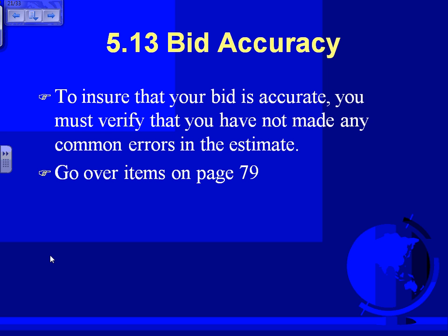Using improper estimating forms, using suppliers' takeoff quantities for quotes. Rely on verbal suppliers' quotes. Then when you get to a written one, for quotes, guys, you always get them written. Because when they tell you $25,000 for the switchgear, they write it, send it to you. They are committed to $25,000. You add them to your bid. When it comes to the point of buying the equipment, they will get you the equipment within the $25,000.